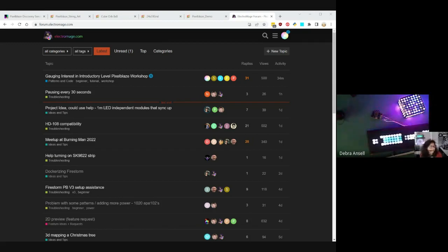Yeah, that's better. I totally agree. Like I said, I was kind of agnostic, and I was like, oh, an extra wire. But it used to be that the timing was a big issue with the NeoPixels too. Most of the plug and play software works around that, and the APA102s are not so timing sensitive because they have data and clock lines to feed the patterns to the pixels. But that's generally not an issue. What I'm going to show now for the coding is this matrix right here that I have out, which is a NeoPixel, but I actually have a nice big matrix made out of the APA102s, and maybe I'll run the patterns on both just so we can see the difference.